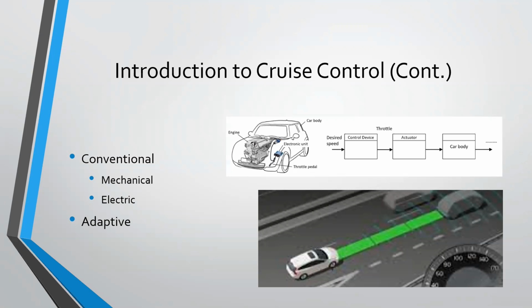In older vehicles where most vehicle systems are mechanical, the cruise control system worked by a mechanical actuator attached to the throttle cable. Typically, the actuator was vacuum controlled and received an input from the speed sensor. When a change in the speed was apparent, the actuator would engage to adjust throttle position to open or close the butterfly valve accordingly, until the desired speed was achieved once again. Since the actuator physically moved the cable, the pedal attached inside the cab would physically move, which could be problematic to some drivers if it was unexpected.